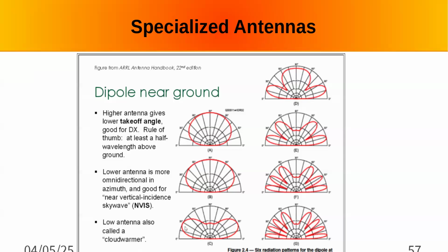So your typical lobes for a half wave at optimum. D is three-quarters wavelength. So see, we got this big vertical lobe now. Our lower lobes are much smaller, with less power in them, because we're sending a lot of power straight up. And then we go up higher to a wavelength. We don't have this upper one, but we have these other higher lobes. As you keep going up and up, you get more smaller lobes.